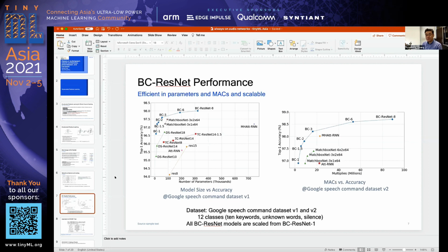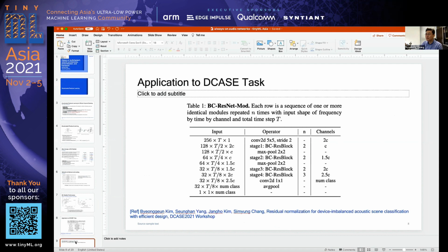Some actually use just the waveform itself. It's kind of an end-to-end approach. The PCM samples themselves are given to the 1D convolution network, and it performs all those convolutions to perform the classification. More commonly, people are using a log-mel spectrogram as input to this network. And we also used that for these experiments, and it showed the best performance.